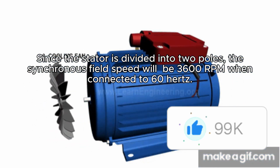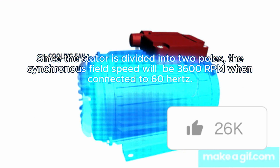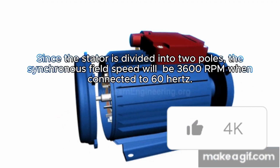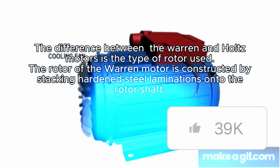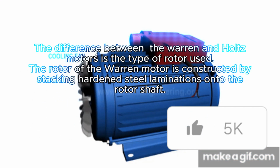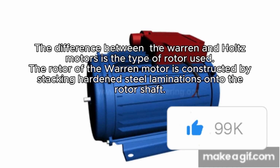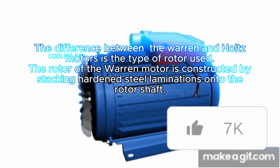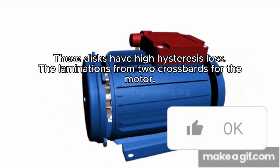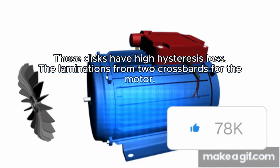Since the stator is divided into two poles, the synchronous field speed will be 3,600 RPM when connected to 60 Hz. The difference between the Warren and Holtz motors is the type of rotor used. The rotor of the Warren motor is constructed by stacking hardened steel laminations onto the rotor shaft. These discs have high hysteresis loss. The laminations form the crossbars for the motor.